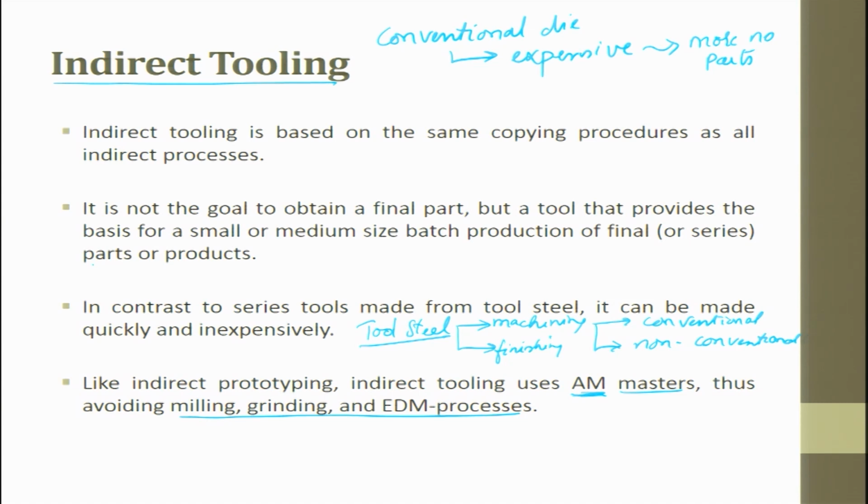And many a times the first die whatever you make, the die designing time itself takes almost close to 45 days. If it is a complex die, it takes 2 months. And it is not the shape alone you have to do, shape and size, it is also the simulation you have to do and find out how the material is getting distributed, what is the load which comes at different points, how many injection points you should have. All these things are too complex to do.